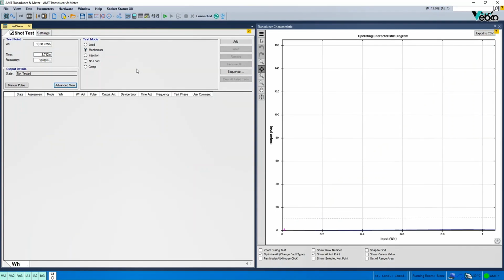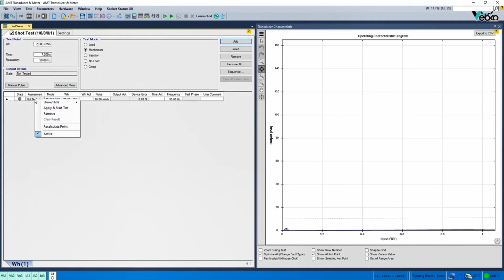Mechanism test. In this section, the injection of rated current and rated voltage is done for a certain period of time to evaluate the amount of transmission energy. The purpose of this test, in addition to evaluating the error rate in the overall measurement, is to evaluate the error rate of the device in measuring various elements.